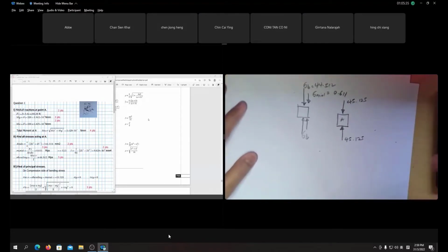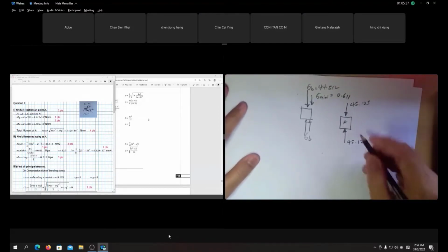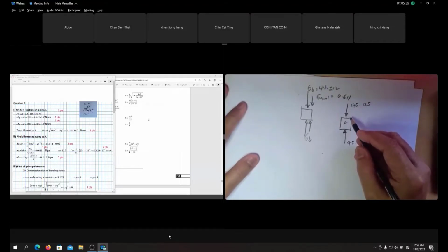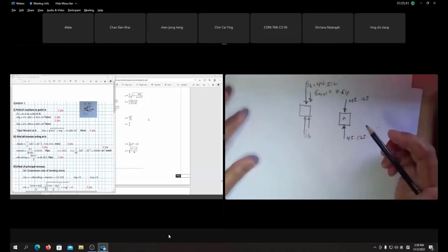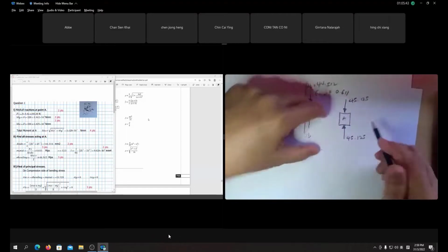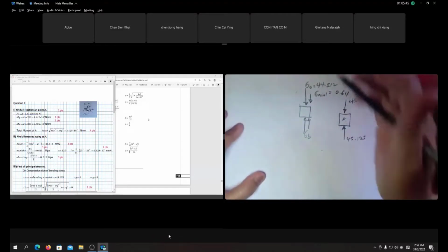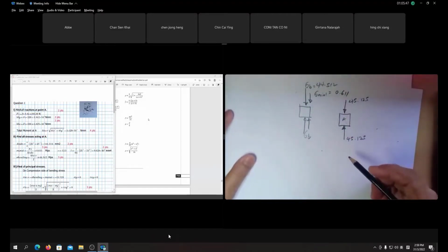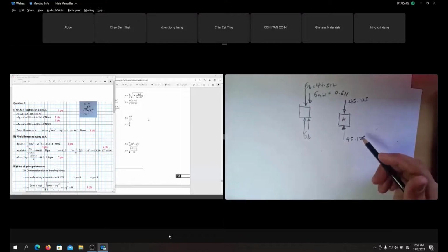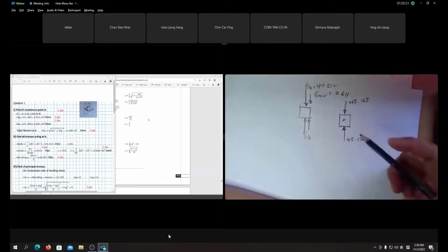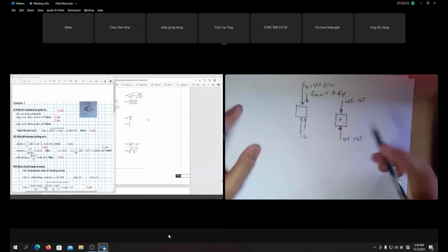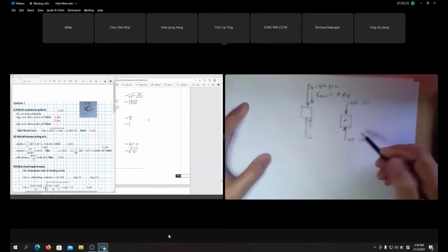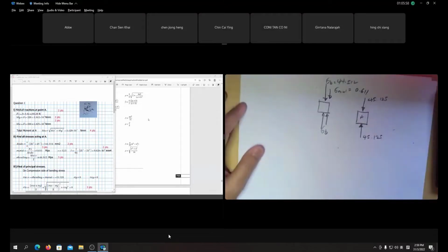Okay, so the stress that happens at A is like this. We don't have any torsional stress in this case, because we combine the bending and the direct axial stress. Axial stress plus bending. For bending we combined Mx and My earlier. Be careful. So we have the total. So this is what happened at A. So that is answering part 2.